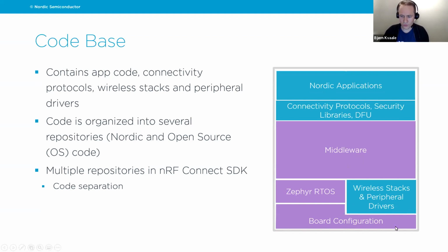I can go quickly through some of the layers. So board configuration, that would be mainly GPIO pin mapping, how to set up the different hardware of the boards. You have the Zephyr real-time operating system. So this is an embedded operating system run by the Linux Foundation. So it is designed for embedded chips. We have wireless stacks and peripheral drivers. So this can include things like the lower layers of the Bluetooth stack. It includes the L1 to L3 layers on the LTE stack.